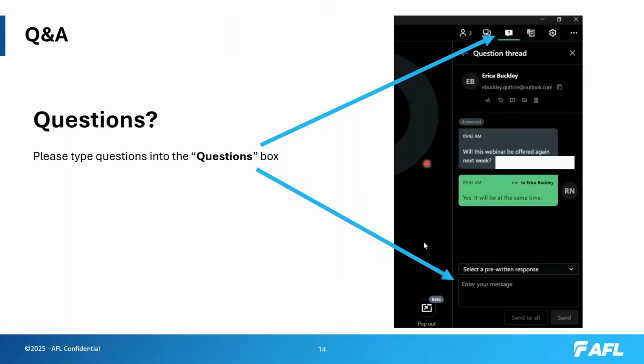I'm assuming you're talking about, we've got two issues. If you're talking about the hot jacket stripper, then you don't really have to change the heating profile. It would still probably be, if it's a rollable ribbon, set at a level of 4. If you're talking about the splice protector sleeve, you could use your standard FP5 setup, and your 12 fiber splice protector sleeve would work for a 200 micron 16 fiber splice. It's a tight fit, but it will accommodate it and it will work. So no changes to your tube heater.